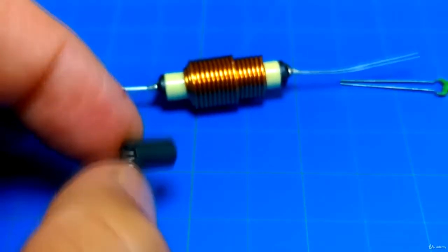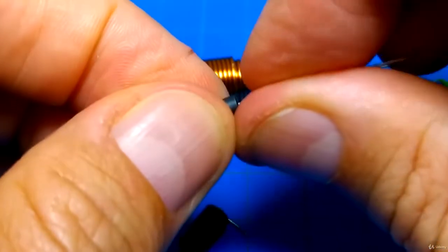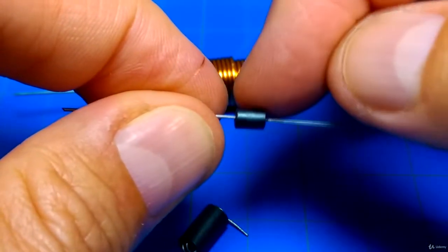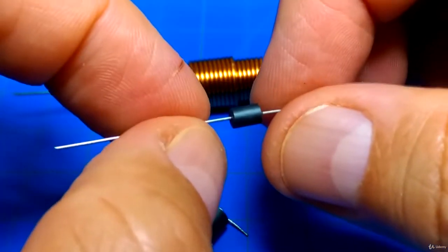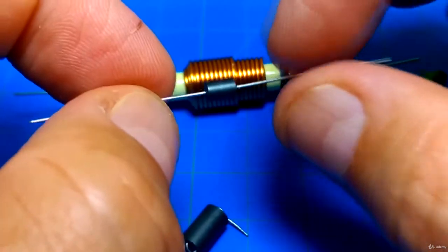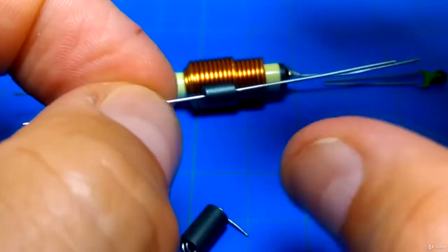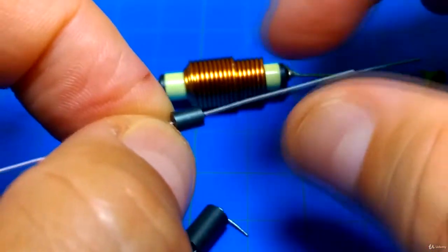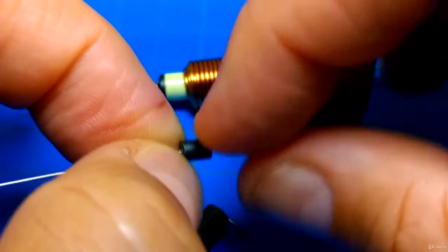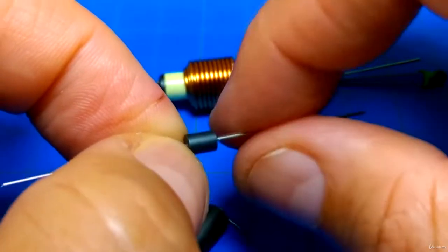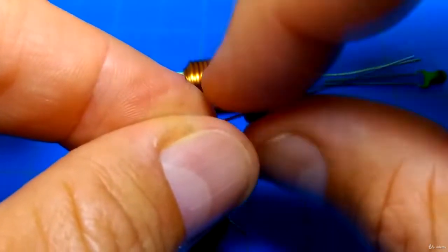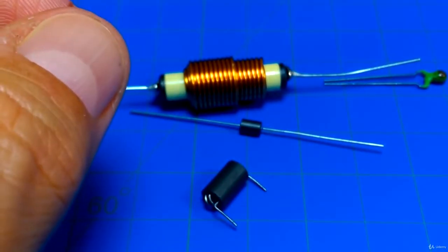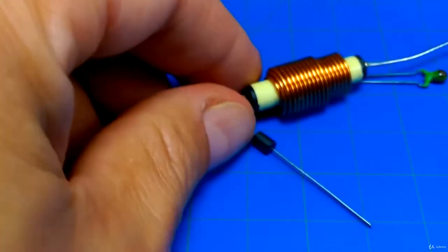So there's one right there, and then here's another one, even smaller. It just goes right here in this one little area, and this is going to be more inductive because of this ferrite. There's going to be flux linkage, and so you're going to get a stronger inductor even though it's just one wire. Every wire has inductance. Every time a current flows through a wire, a magnetic field is generated. But when you put this ferrite on it, it changes the properties of that. So again, that's axial, and I think that's about it of those.